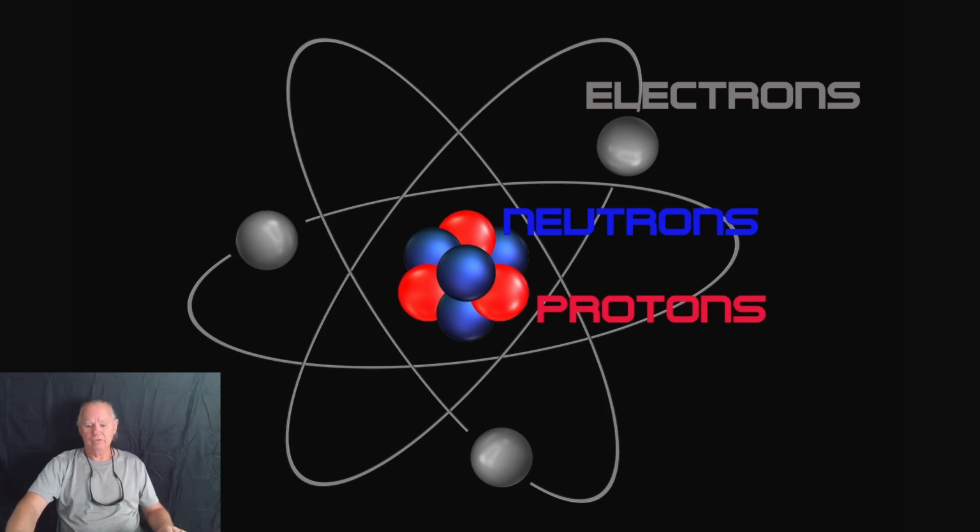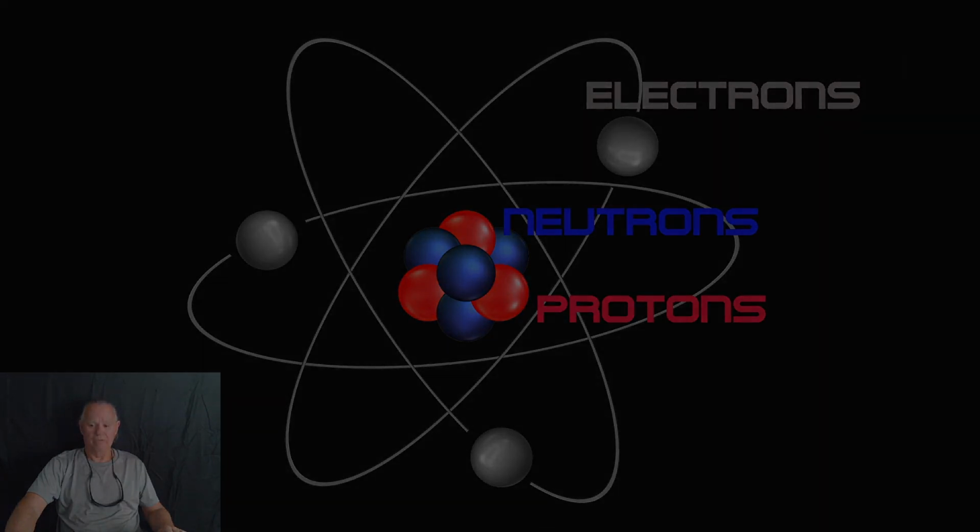And conductors have 3 or less electrons in the valence shell, and the valence shell is the outer shell where the electrons orbit. They produce a freer electron that is able to escape easier, being as they're in the outer shell. Now, conductors have 3 or less electrons in the valence shell. Semiconductors have 4 electrons in the valence shell, and insulators have 5 or more electrons in the valence shell.